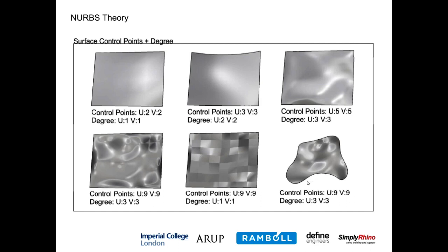So when you trim off parts of a curve or parts of a surface, you're not actually getting rid of any control points there. That grillage still exists behind the scenes. What you're doing is adding an extra layer of information which just tells Rhino this part of the curve exists, this part doesn't. And the reason I mention that is because you may find sometimes in Grasshopper some components will take in a trimmed curve, but they will still treat it as if it's the full untrimmed curve, or even the full untrimmed surface, that you started from.